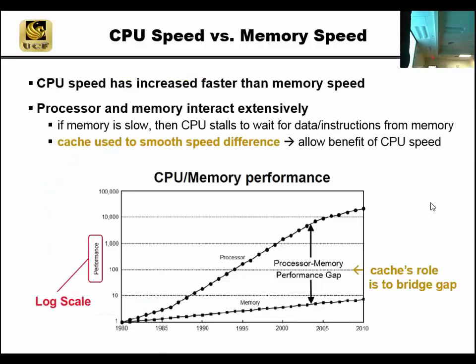So if we look at the aggregate of these effects, this is processor performance. We said measuring performance is difficult. Take execution time for a benchmark and look at the percent of time spent on processor-intensive instructions, ALU logic, versus load store, which is data transfer. Memory has not improved at the same rate that the processor speed has improved. Why? Because it turns out storing a bit is a hard thing to do. It's counterintuitive. Making a full adder seems more difficult than remembering if a bit's a 1 or a 0. But remember, if a bit's a 1 or 0, we haven't come up with any breakthrough ideas how to do that. We'll show you a few different designs.